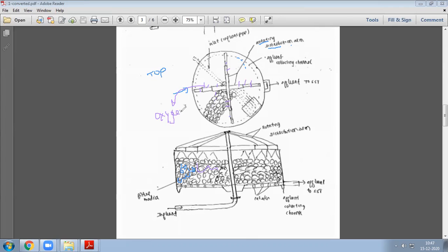Traditionally, in the previous method, we used to enhance the oxygen level. We used to provide diffused aeration or some variation, installing some pipes to give oxygen. But here the oxygen is already there in the atmosphere, so we try to make every drop get exposed to environmental oxygen, so it will gain oxygen and then fall onto the coarse bed.